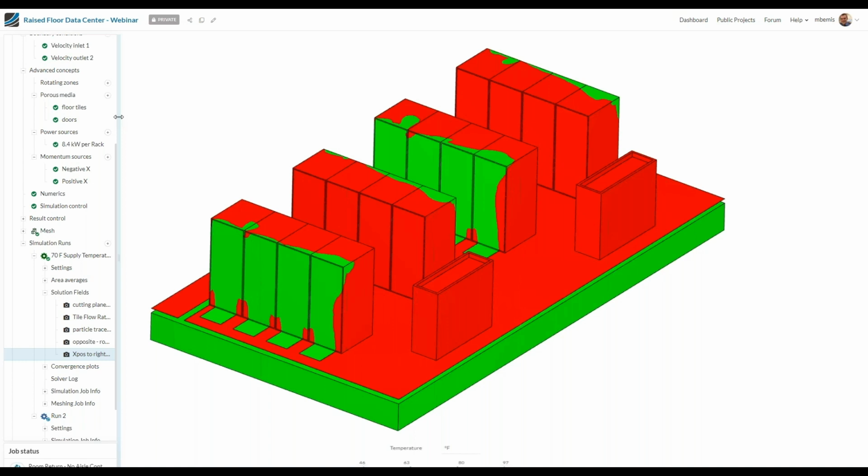Green means we're between that 64 and 80. We don't see any blue, but a lot of times data centers are too cold. And red means you're too warm. I think the areas that really jump out to me, let's say right here, if you see my cursor, the farthest to the left row, and it's always the rack at the end of the aisle, right next to the CRAC unit. Now we've got too warm of an area here on the right side of the rack. Same story, a couple rows down here as well.